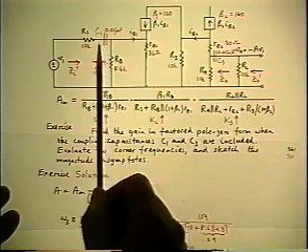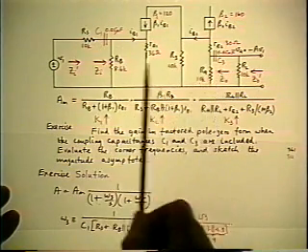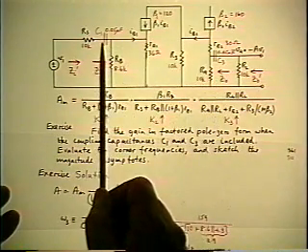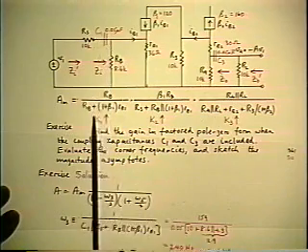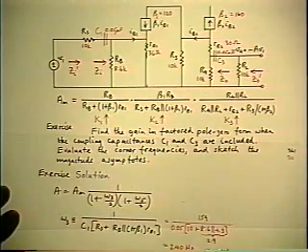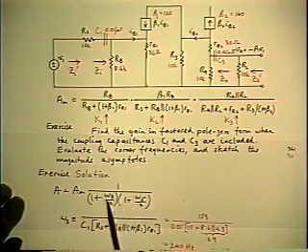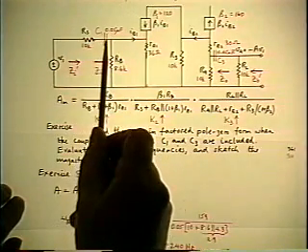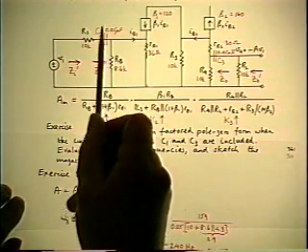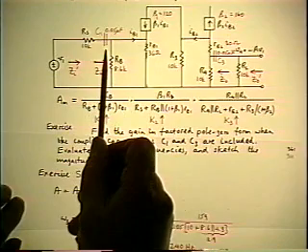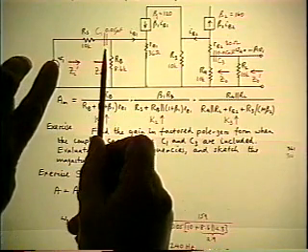So the reference gain is the high frequency gain, and we'll use the version of the extra element theorem for an extra series element to put the C1 in. So the process is, again, doing it all mentally. You replace the extra element by the independent source, and you calculate the resistance, RD, looking in under conditions that the V1 is 0.